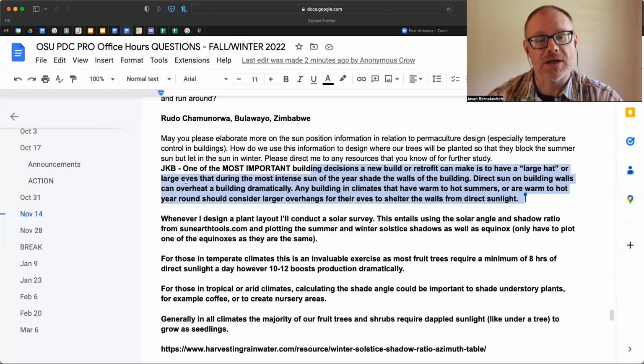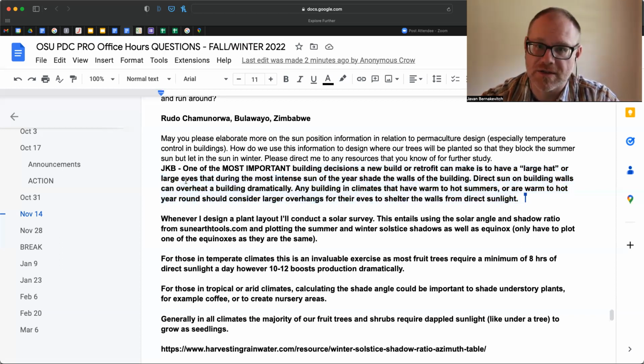And then during the winter, they were cut for leaf and they were just basically pruned back, so that way they could have more sunlight. So generally what we're doing is we're trying to choose trees at height and foliage to occlude as much sun as possible during the hotter times of year. And then on the other end, we're trying to make sure that they drop those leaves during winter months, so that way we can get the most amount of sunlight possible to areas that we need. That's generally what we're trying to do.